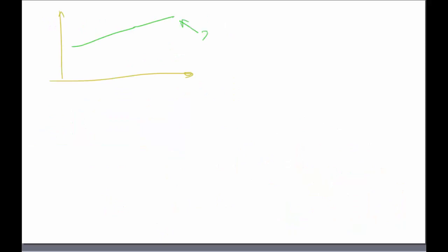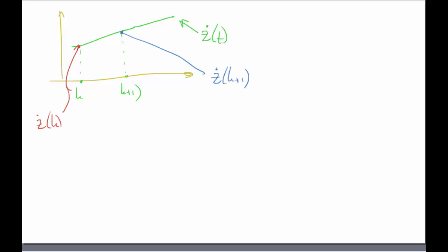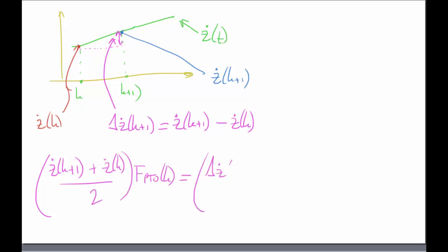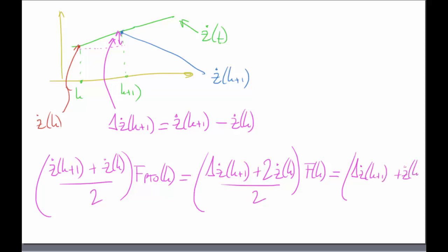You're probably wondering why I used a delta z dot value. I've seen other methods where you use a backwards and forwards Euler's method, but this brings up errors in the optimization, which has a knock-on effect with the actual power absorption. So this is a closer estimation of the power absorbed. You can see here that delta z dot is the difference between that instantaneous z dot value minus the previous value. So when you fill that into the equations that you saw on the last slide, you get this value here,